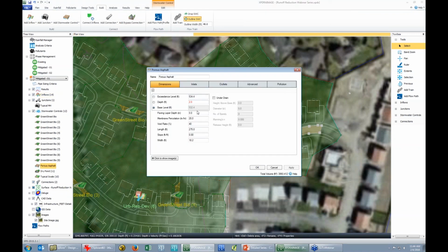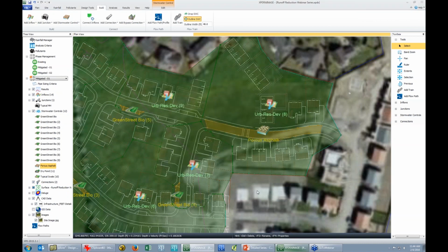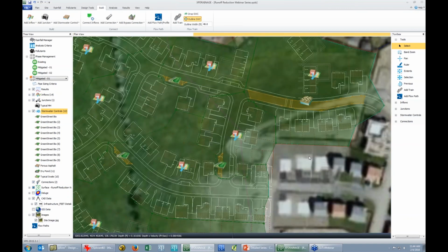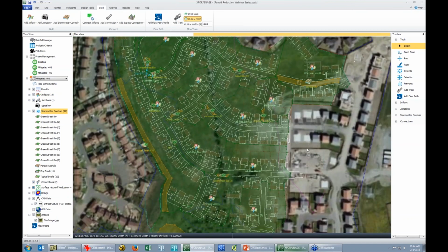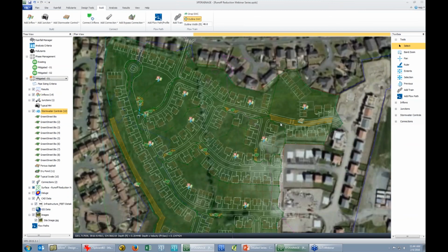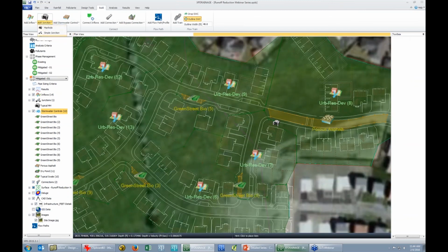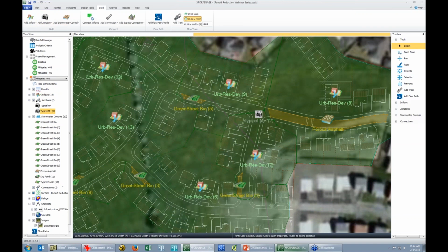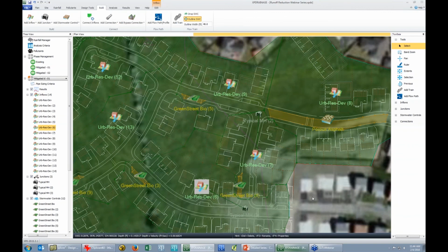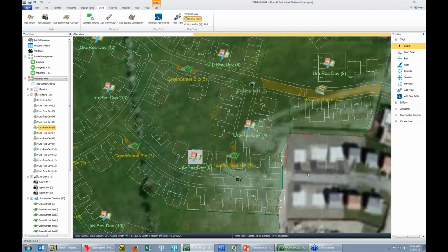So based on how we drew it, the elevations, okay, we get that area, we've already input this void ratio, what have you. So that's as hard as it is. We could add in manholes to allow for collection. So I could say I just want a typical manhole. And I know there's going to be kind of collection at the various intersections. Okay, right? So I applied a manhole here, and you see it snapped that this area drains to this. Well, we could change those. That's all there is to it.